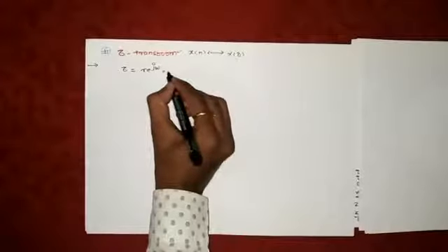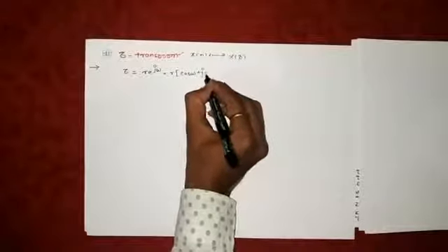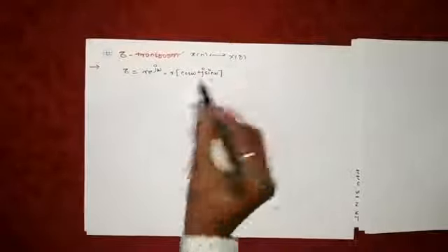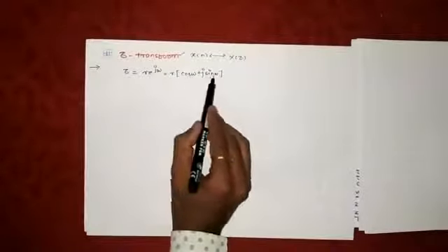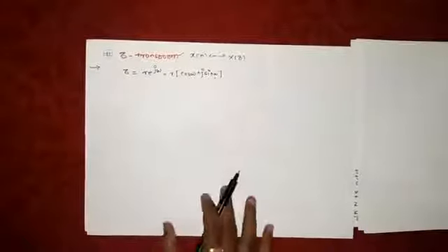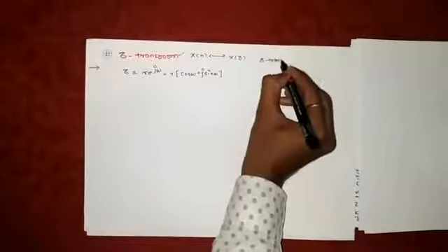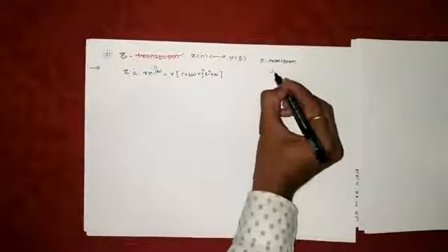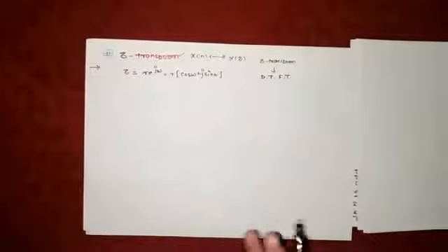Now, this r is nothing but the radius, and this is an exponential function. If I simplify this, I can write this term as r into cos omega plus j into sine omega. That means it is a complex exponential function, as well as a complex number, cos omega plus j sine omega. So they are used to represent these complex functions. Next, the equation for Z transform can be obtained from a technique that we already discussed, known as discrete time Fourier transform. So let us take help of discrete time Fourier transform and we'll come across Z transform.